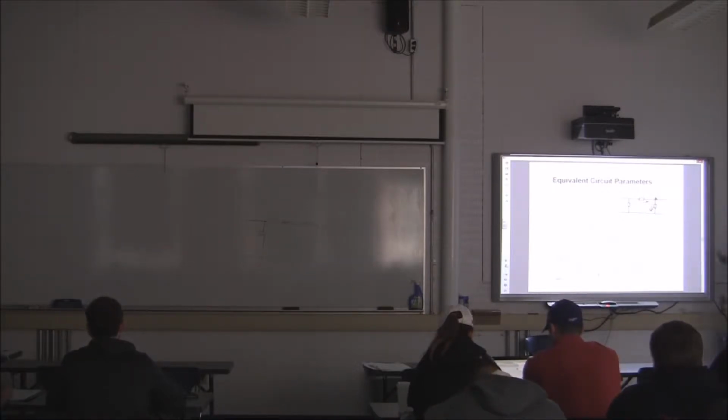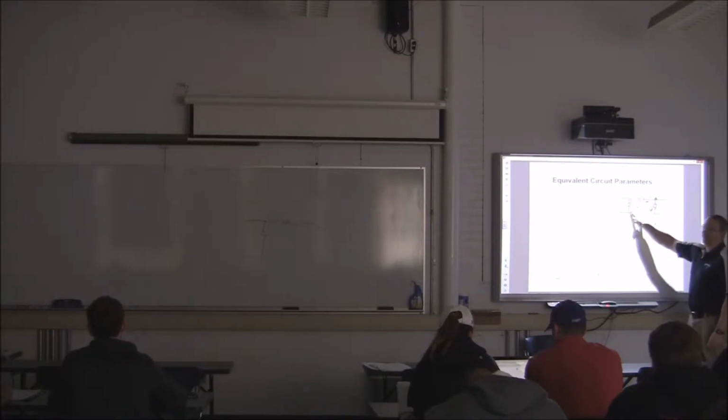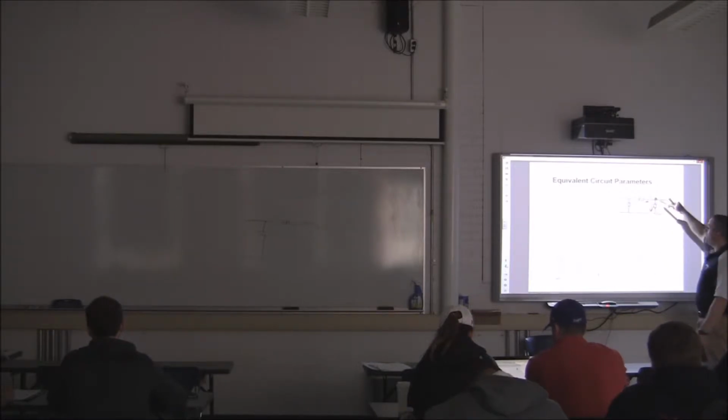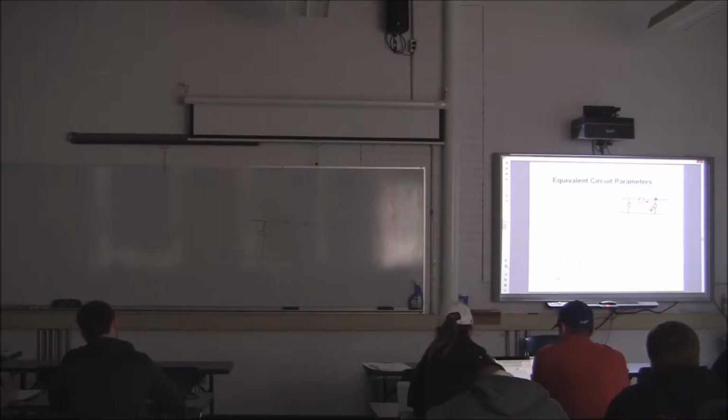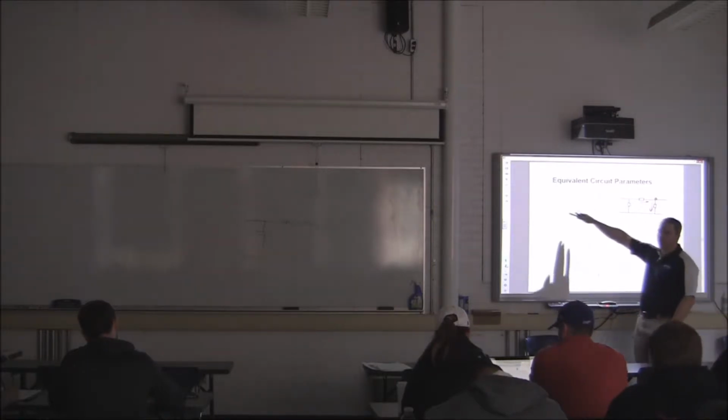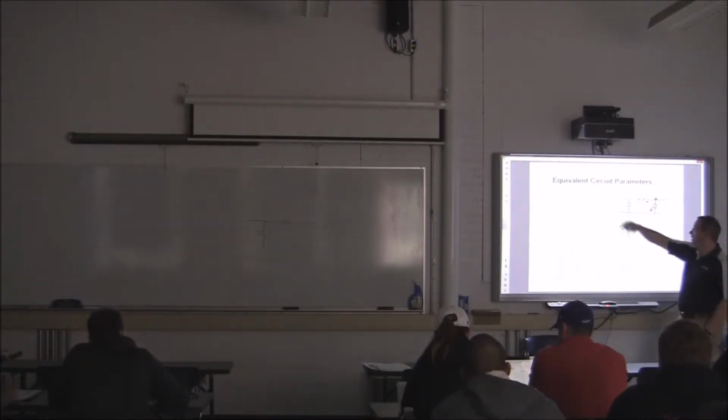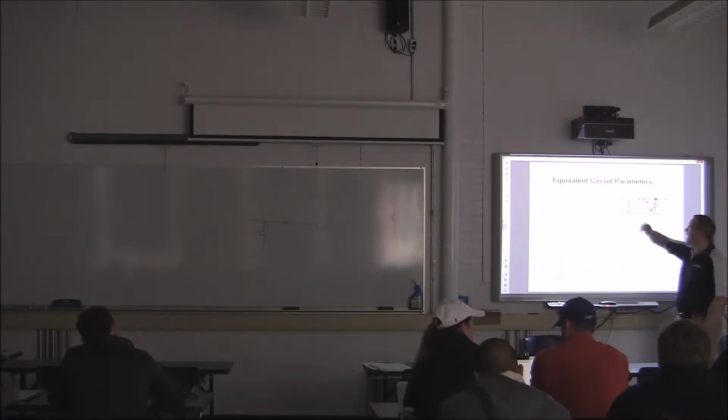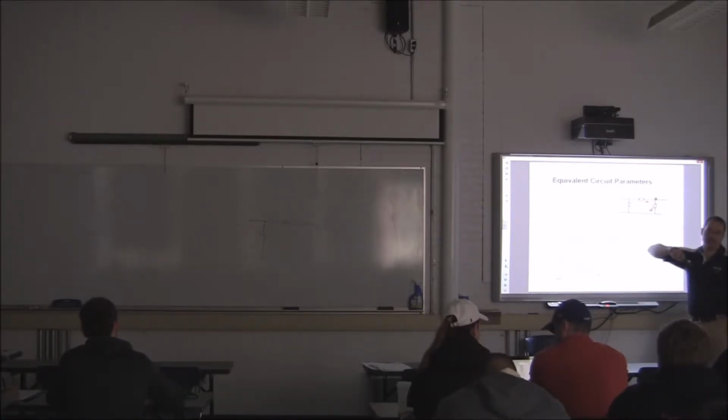So the current into the node, this is Vs, right at this node. This node voltage is VR. I know the impedance between them. Can I write a node equation, a current equation for that, knowing that information? It's Ohm's law, right? Vs minus VR divided by Z prime is my first current. That is this current here.